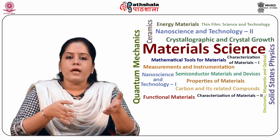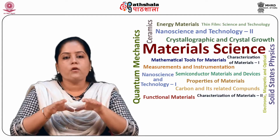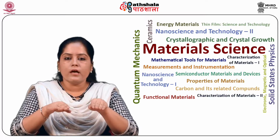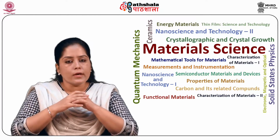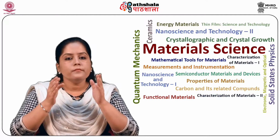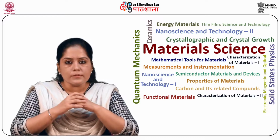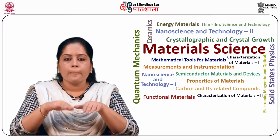These traps are deep donor levels which can cause reduction in drain current, enhancement in low frequency noise, and photoconductivity. This further creates problems, particularly at low temperature.